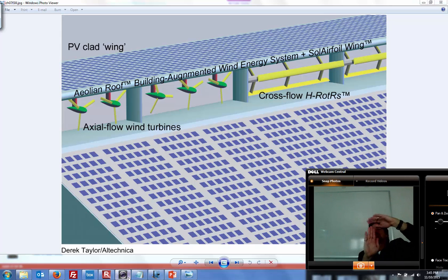Anyway, so you put a big pool of oil, some type of lubricating surface, and a big block of lead, concrete, something massive. So now, when the building wants to vibrate, the big mass at the top dampens it. So the building was re-engineered to reduce the amplitude of its resonant frequency of vibration.